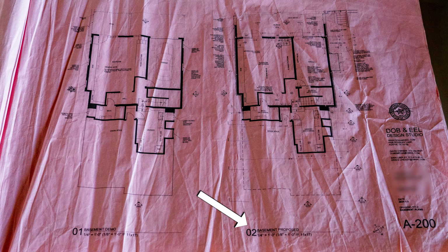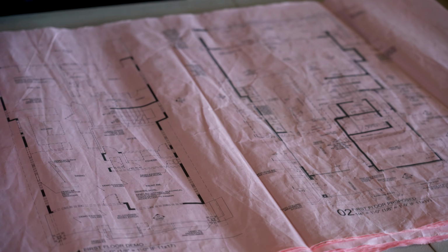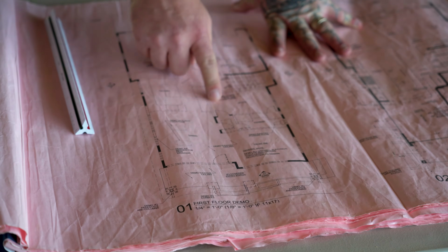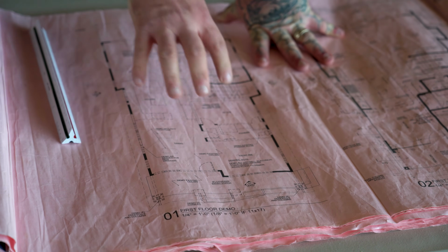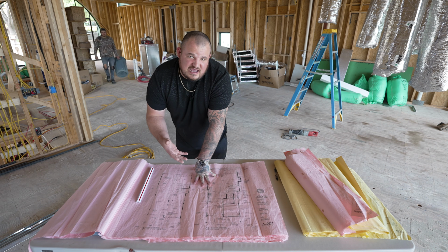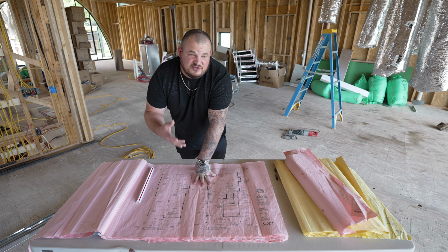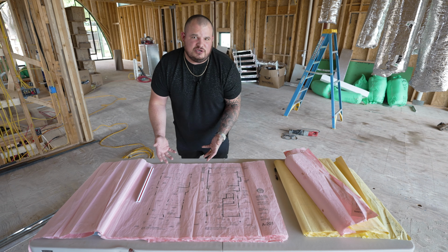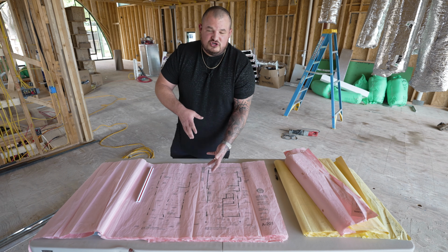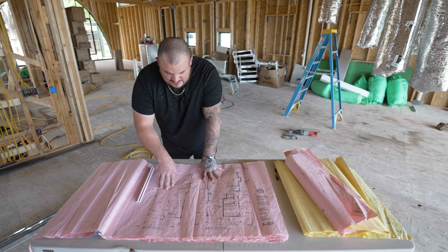Now this is our basement, which we're not doing that much work to, but let's move into this level plan. So as you can see, this demo plan, all of these hashed lines mean those are the walls that you are removing. And then, you know, there's different types of remodels. If you're going all the way down to the studs, the demo plan is going to note that. But there's also times where we're just doing a kitchen, right? So maybe we're just demoing portions of a wall or portions of the cabinetry or keeping certain fixtures. That should all be noted in the demo plan.